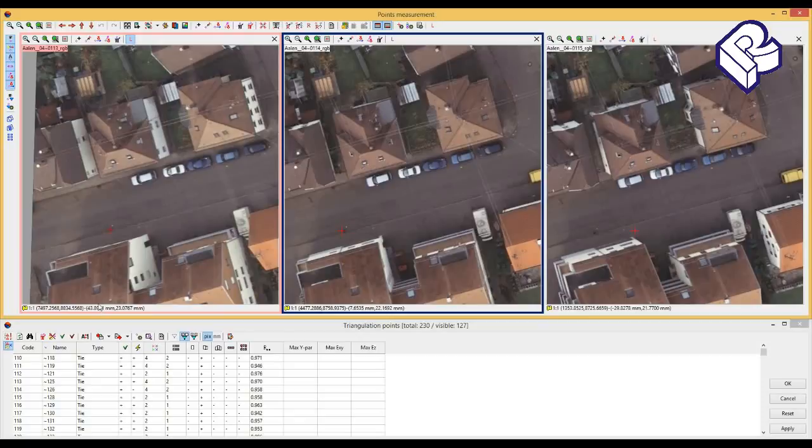Remembering that camera pixel size in x-axis is 12 microns, calculate that a survey basis equals 38 divided by 0.012, which is 3166 pixels.